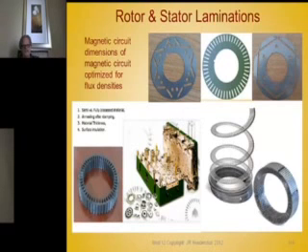This is an interesting way to make a stator. This is a slinky method. It's a very clever method to make a stator, because with a fairly thin cross-section yoke and tooth, if you punched that out of a completely round or a square piece of steel, you'd have a lot of waste. You'd waste the corners and the ID, unless you could punch the rotor punching out of it. So that's a very great way to make stators. It's been used for many years, originally patented by GE in Fort Wayne, but the patents have all run out, and now this is made all over the world.